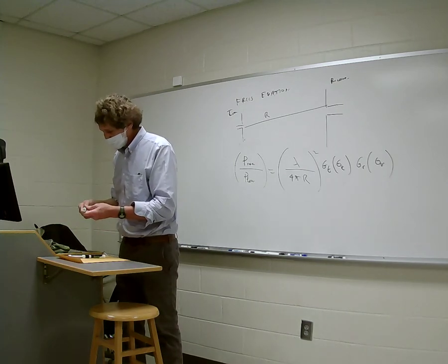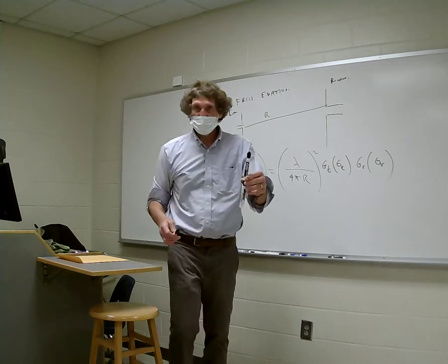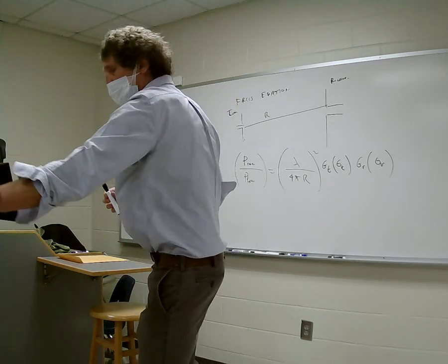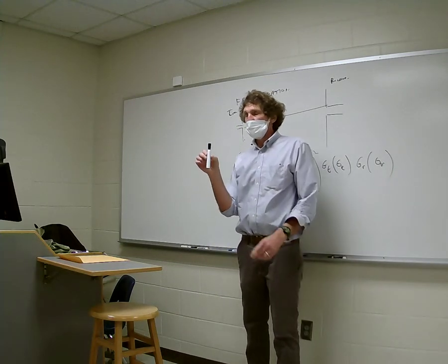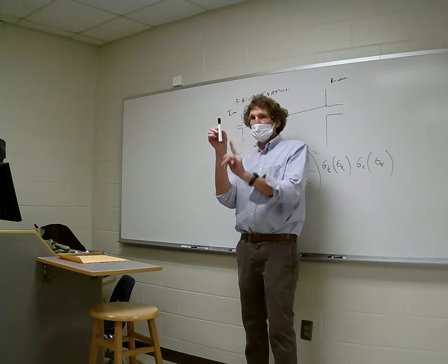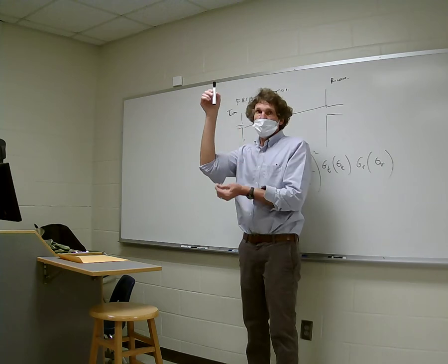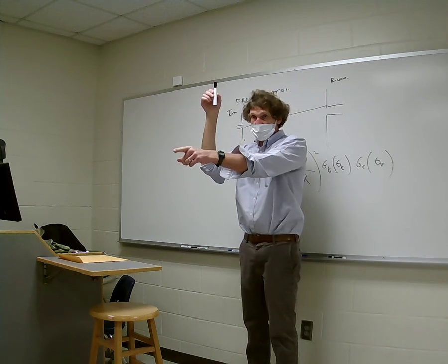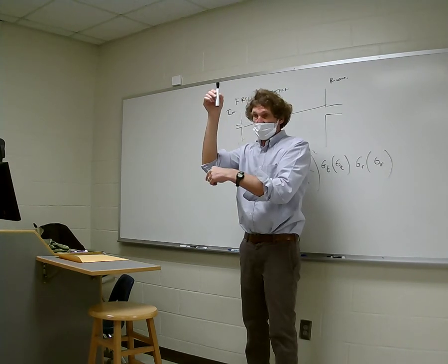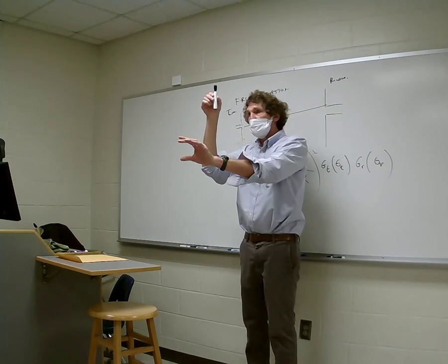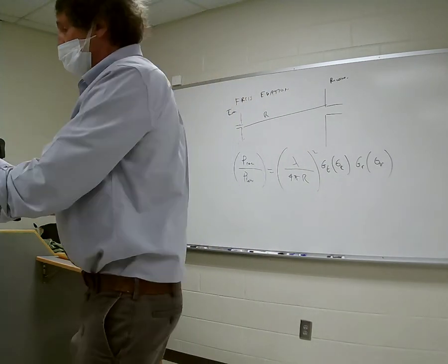Suppose I have an antenna, you hold that. Now keep an eye, it's vertical. Hold it in the middle. All right. I've got them both aligned, and you see this one's going vertically upward, that one is, right? If they were both short dipoles and I wanted the total power received, I could get power transmitted over 4 pi r squared. That would be the distance. You all follow me? Then I'd multiply it by the gain. What gain? 1.5 times the sine squared of the angle measured from this axis to the radius vector.